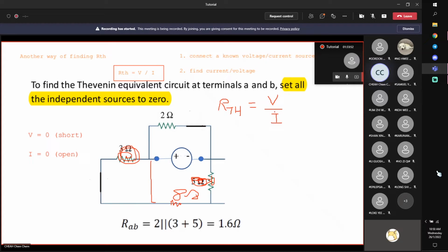Now in an experiment, you just measure the flow rate: connect a source, measure the flow rate. In circuit analysis, you calculate the flow rate. And V over I is equal to resistance. This means that instead of finding the resistance directly, I find it indirectly by using the voltage and current. Usually we put 1 volt. Why? Convenient. If voltage is equal to 1, then 1 over I is your resistance.